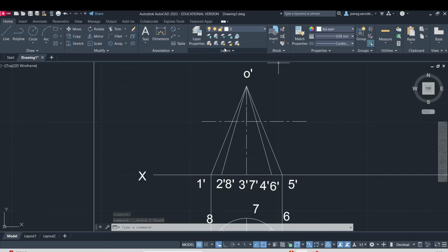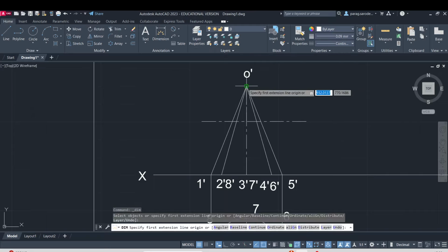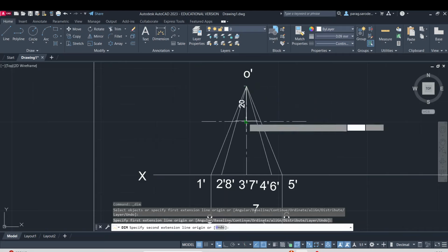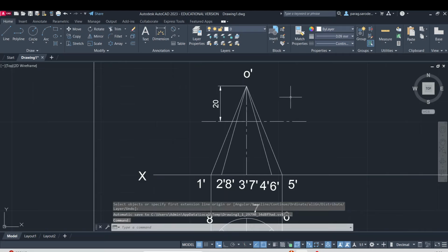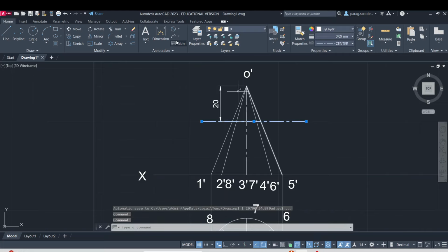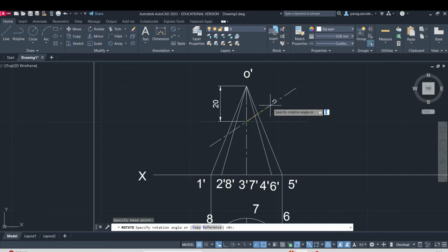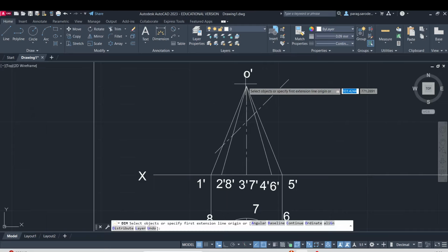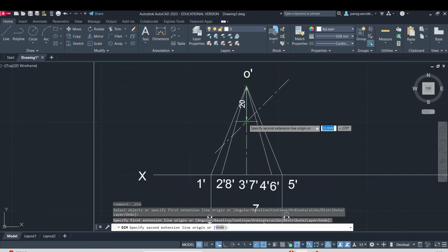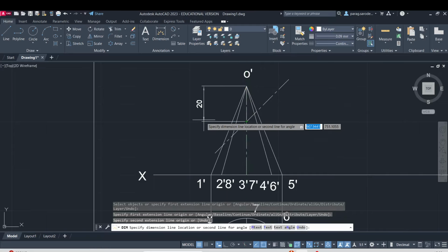So retaking the dimensions again. So this, okay, like this. Now we want it to be inclined at an angle of 45 degrees. So let us click on rotate, and then we'll keep this base point. And what is the angle we require? 45 degrees. So we see that it is now inclined, right? Now the dimension point is changed. So we will take these dimensions from the apex to the point on the axis. We see that still the distance is 20.